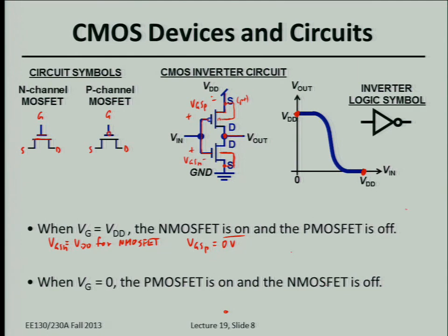So basically then what you have as a circuit is, ideally, an open circuit between VDD and the output, and you have the on-state resistance of the NMOSFET, we'll call it R on, connecting the output node to ground. Right, so ideally the PMOS device is off, so there's no connection between supply voltage and the output.